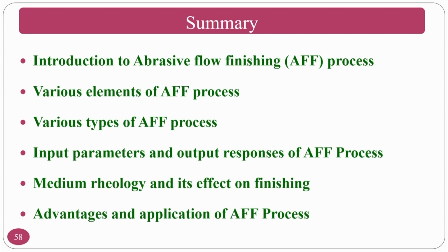As I said, in this particular process the finishing rate is less, because of which the time taken will be very high. If the time taken is very high, the medium viscosity goes down. For that purpose, in the upcoming classes we will see how to improve the finishing rate by providing rotational speed to the workpiece, rotational speed to the medium, and vibrations to the workpiece. How these all work, and other things, we will see in the advancements of abrasive flow finishing process.